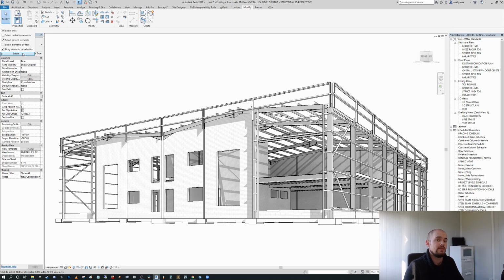And this is actually what I recommend. You can select links, which means that you can turn that on and off in a project. If you're, let's say, the BIM manager or a BIM coordinator across a team, and you don't want people freely selecting elements within external links, you can turn that off in the model, and you can instruct users not to turn that on, and they will not. Actually, I think it's an instance option within the Revit toolbar, but you can instruct people that select links is not available, and then they have to turn it off, and they're just not able to tab select the link.